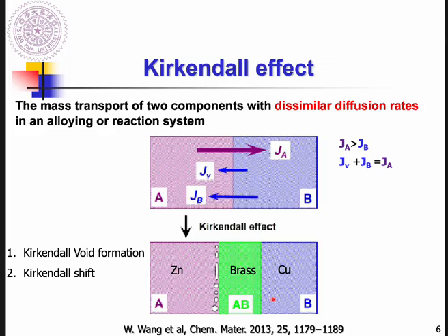And following, in order to explain this Kirkendall effect, we need to explain how fast or how slow this interface or void formation moves. We need to learn the diffusivity, this term, and we do have different diffusivity based on different reference coordinates and also different material systems.